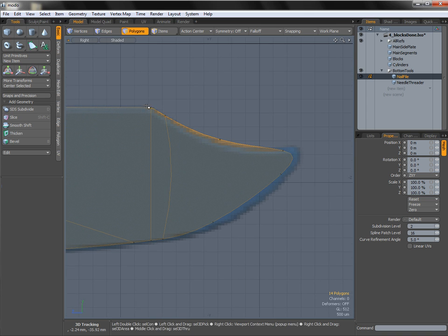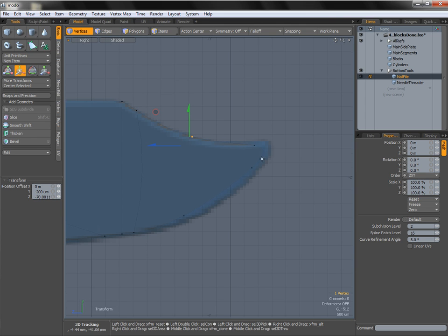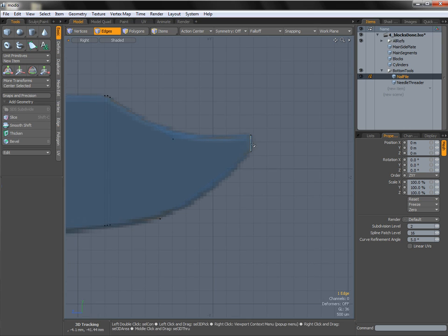So we're going to carry on going clockwise around the mesh. We've got this vert, which I'm going to move down a little bit. I'm going to follow the background reference image like that. So about there, looks pretty good. And then obviously we've got this problem at the end here. So out of tab mode, we'll take a look at what we've got. We've got this end edge here that we want to stay right at this point on the z-axis, and obviously when we go to tab mode, it's being pulled slightly to the left towards all of these other verts that are quite close to it.